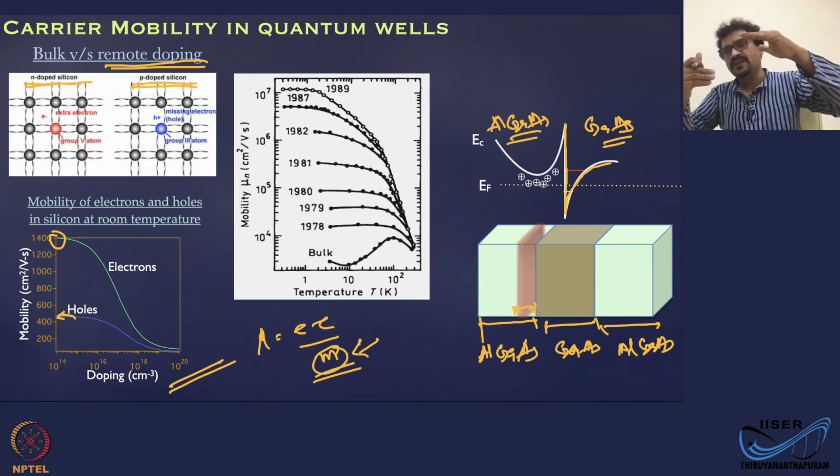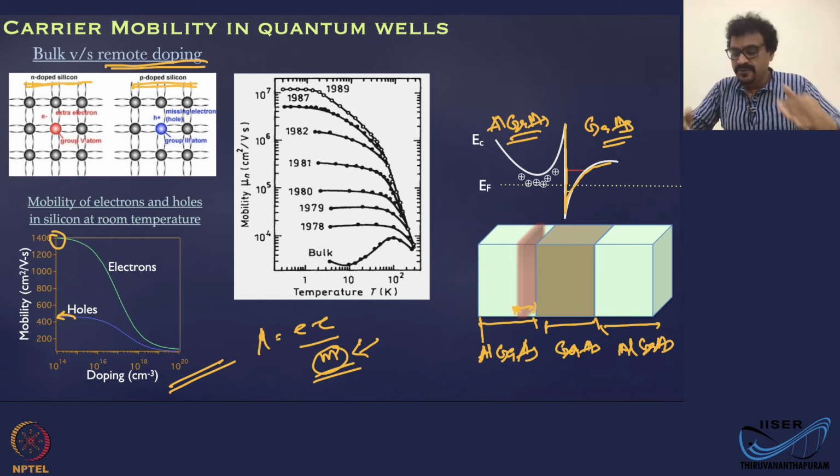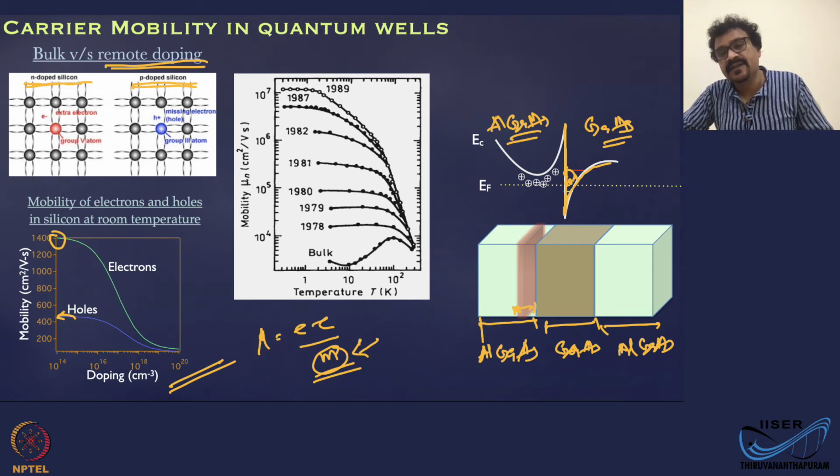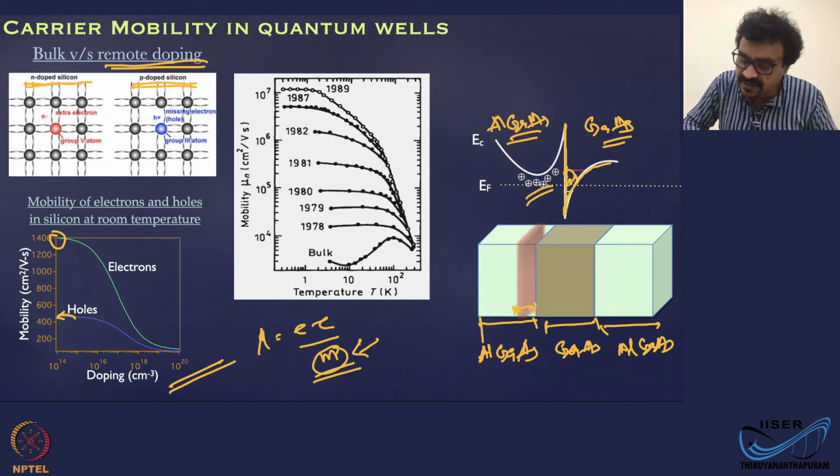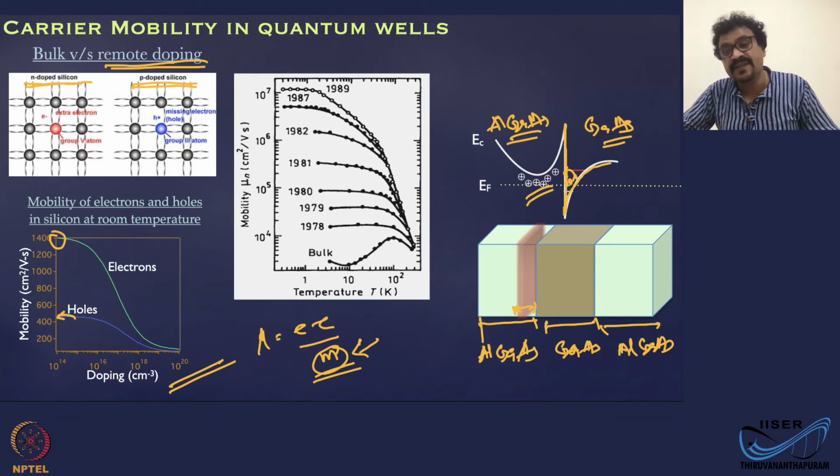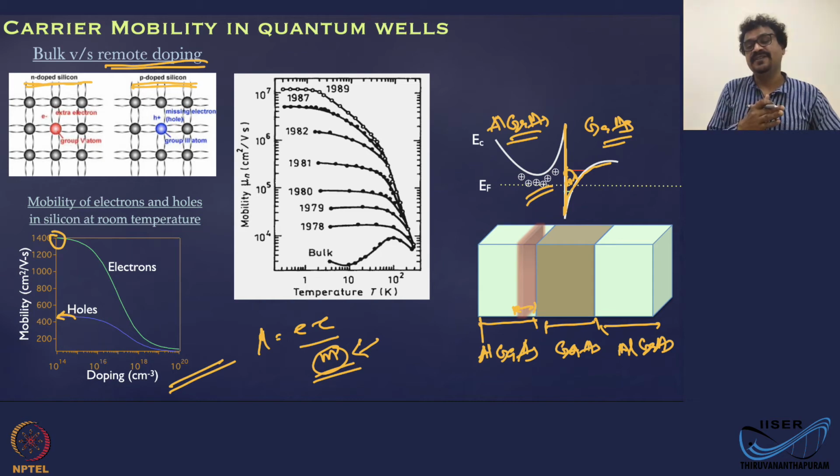The electrons can spill over. But now there is a potential barrier here. So these electrons which have spilled over cannot go back because of the barrier. But now the triangular well will hold these electrons, and these electrons will be pulled by these ionized dopants here. There are dopants from where these electrons came. They will try to pull the electrons back, but they cannot go because of the barrier. So the electrons will be almost like pasted onto the wall. Kind of, it's not pasted, but it's moving very close to the wall.